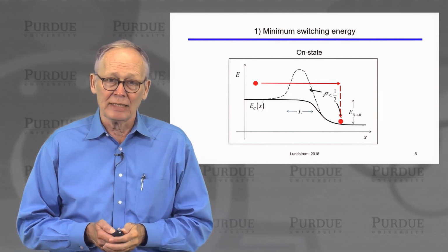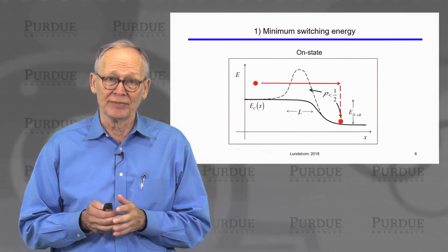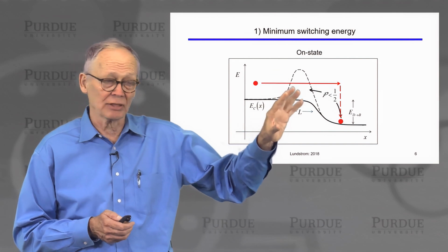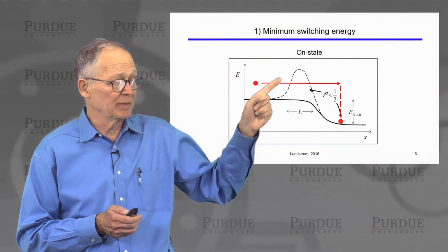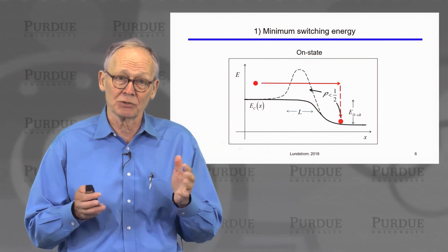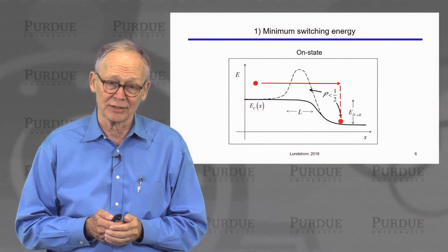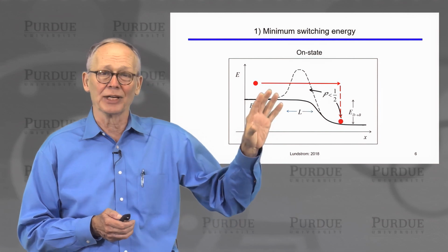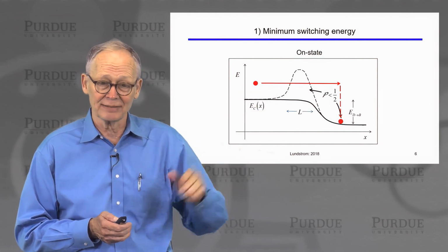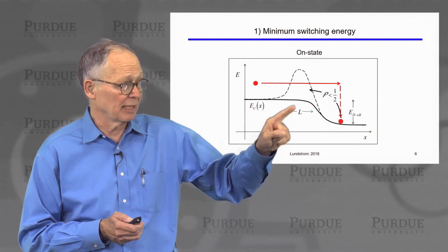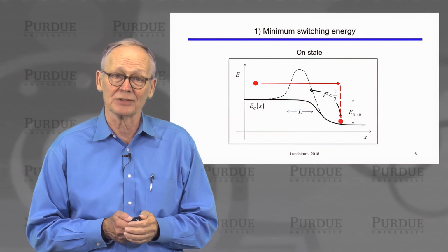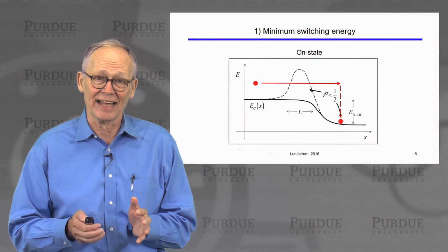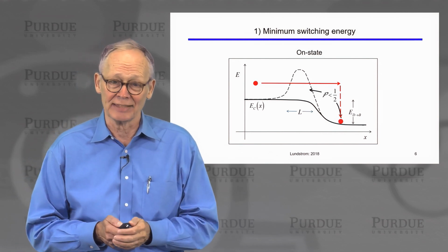Okay. Well, if we have a switching event, we have to ensure that when electrons get in the drain, they can't be thermionically emitted and go back over the barrier into the source, or else a switching event has not occurred. So we have to require, from a fundamental perspective, that the probability that an electron can be thermionically emitted over that barrier and go back to the source has to be less than a half, so that a switching event did occur.